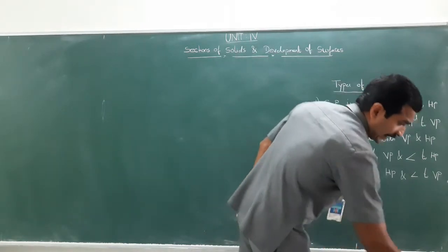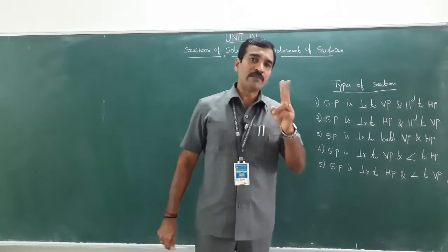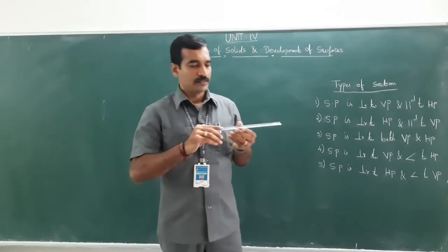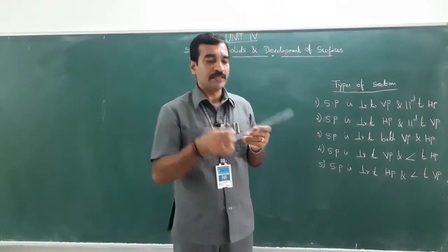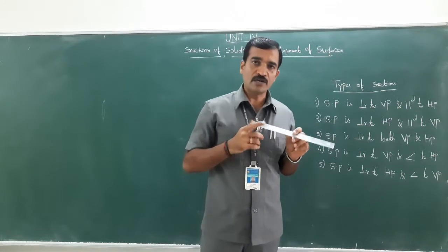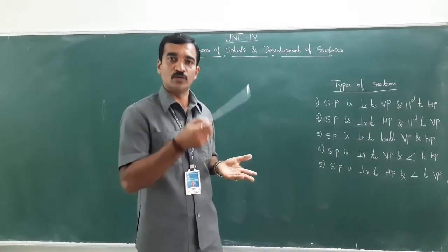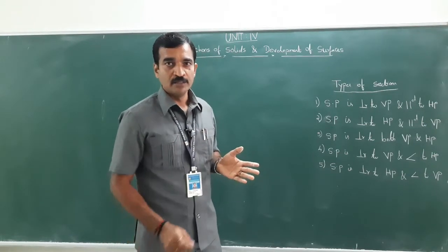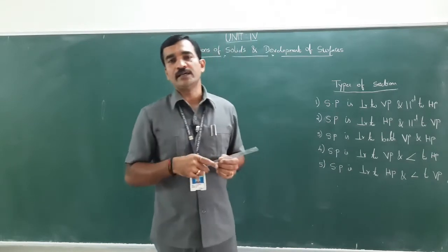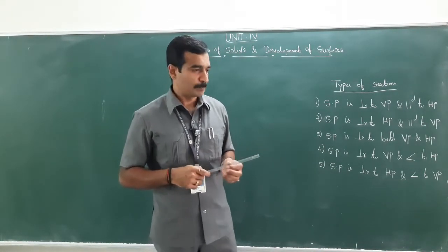See, section plane and cutting plane. What do you mean by plane, by the way? A plane is a 2-dimensional object. It has only length and breadth, assume a scale. This is length and this is breadth and negligible thickness. That is called projections of planes. So section plane is also in that manner only. It's a 2-dimensional object. The purpose of the section plane is to view the interior portions or the hollow portions of the solids, right?